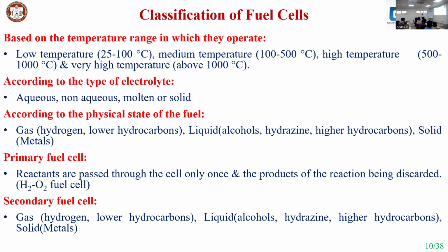So you need to select the right material for the anode, cathode, electrolyte and also the gas diffusion layer. The material you use in the anode and cathode does not take part in the reaction; it only reduces the activation energy and increases the reaction rate happening on the anode side and cathode side.